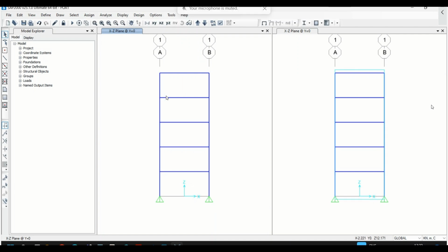Specifically at the member level, the ends of the beams and the ends of the columns, frame members will yield or enter into the plastic rotation state. So we assign hinges at those locations. The program allows you to assign hinges at desired locations, but we'll be assigning only here.